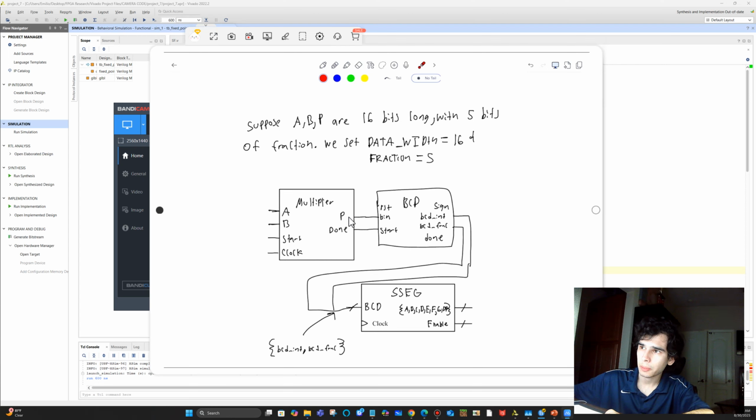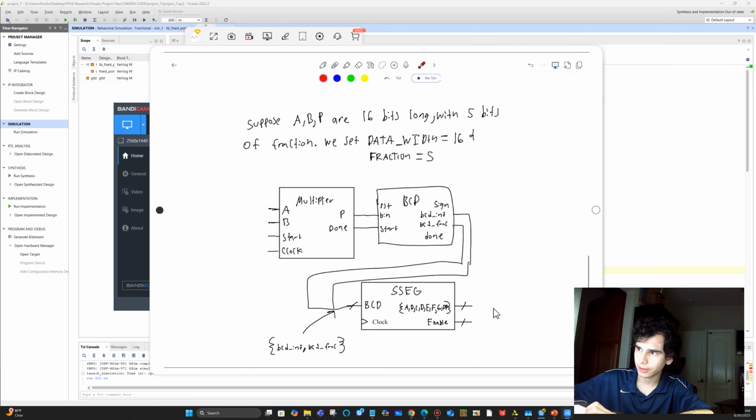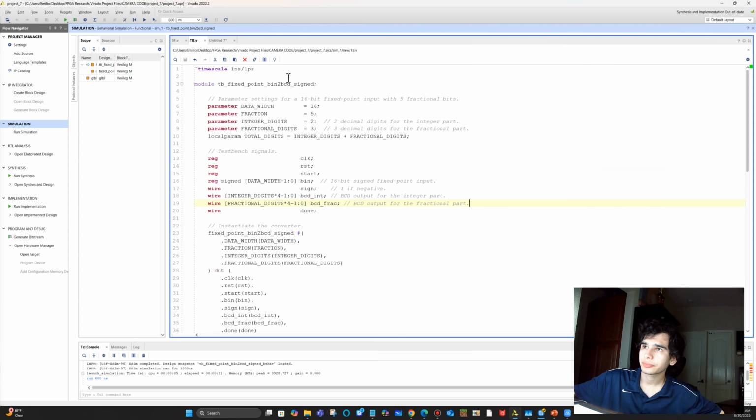we cannot just pass that value into the BCD and expect it to drive these two arrays in a way that will generate the 7 segments to show the value that it is. It's not going to do that. What we need to do is pass it through this module, the BCD module, to convert it into a format that can be used by the 7-segment controller module to correctly drive it. So it's not too bad.